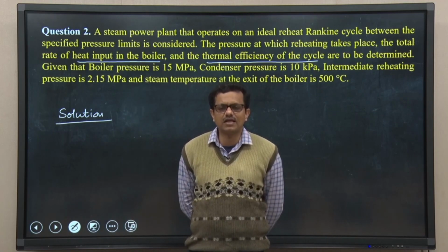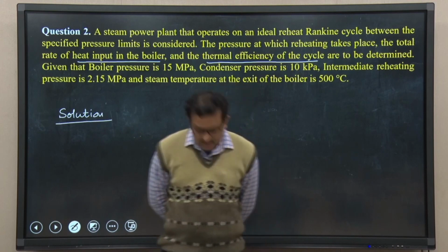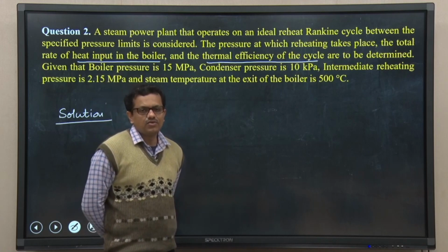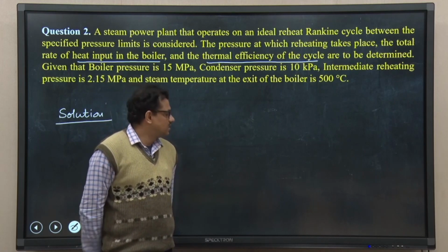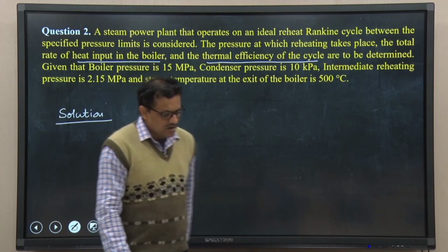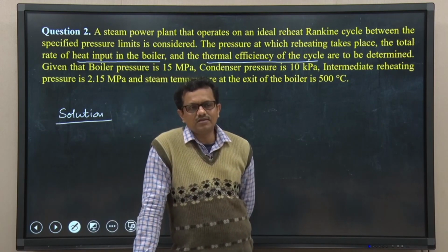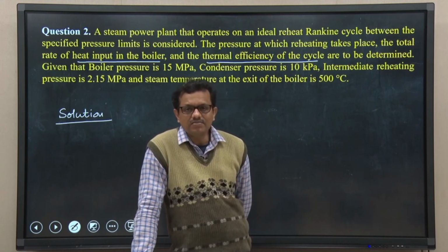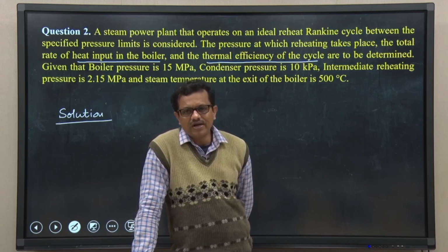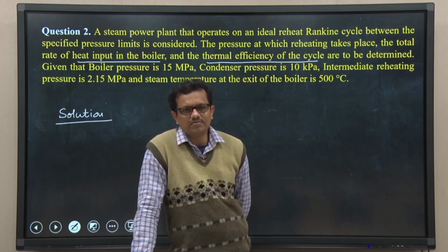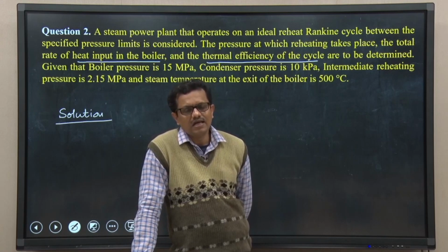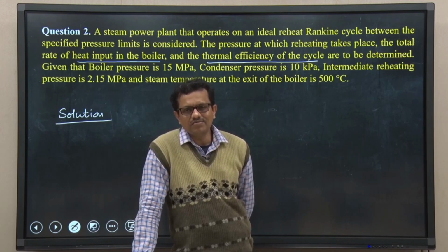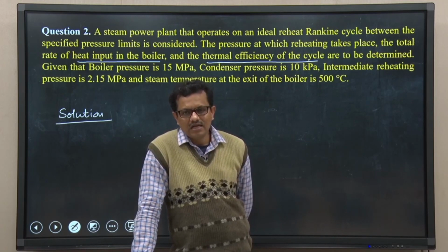But we have also discussed several demerits associated with these modifications, and out of these three important modifications we could discuss superheating steam beyond state 3, that is the state point at the inlet to the turbine. If we can superheat this steam, efficiency can be increased.